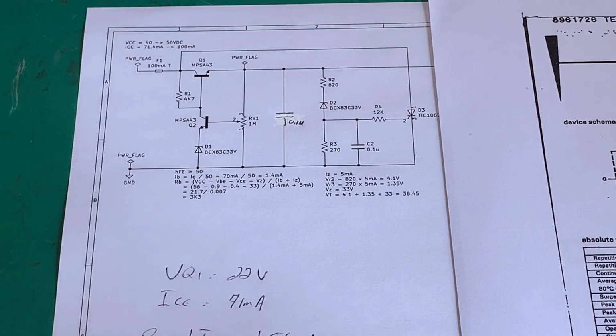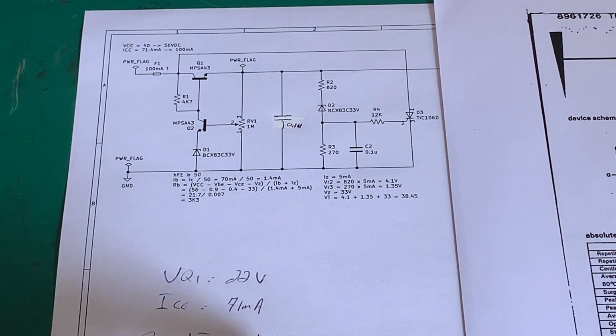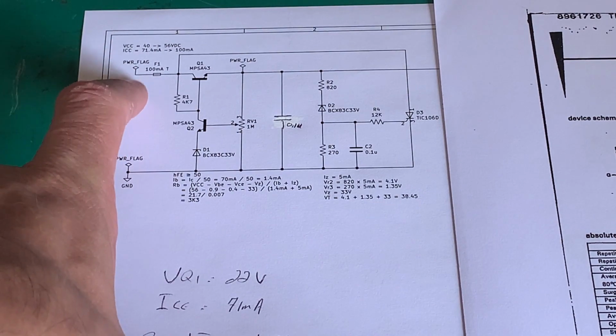So what he's trying to do is make zones, so different circuits in the house. For example, your geyser is on its own circuit, your stove is on its own circuit, certain plug points will be on one circuit, another few plugs will be on a separate circuit, certain lights will be on a circuit.